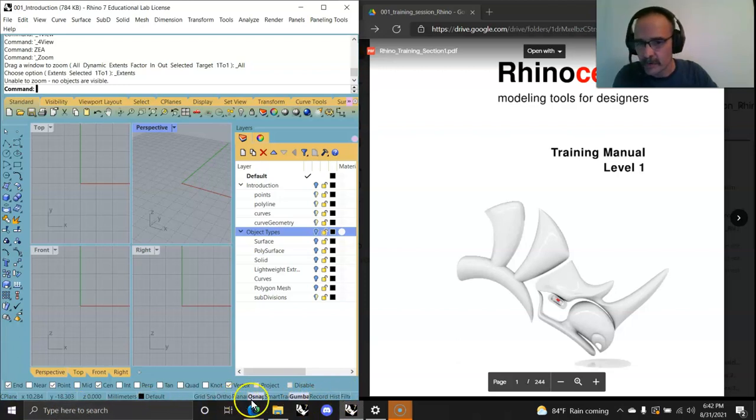And then the object snaps, if you're using object snaps, you're going to want to find out how to end up getting these. I believe if I hit shift and click here, it has a nice transfer over to, maybe it's control. There it is. Control will bring us into tangent from a long line. People don't know that there's a whole advanced set of object snaps, which are really nice to know where they are. I'm going to keep on center, point, and end. Sorry, it's coming up by this little counter.